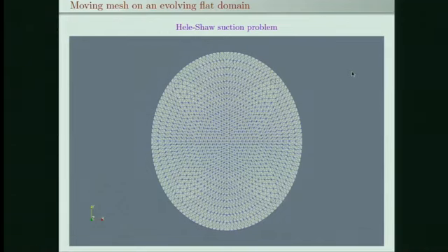We have a discretization on half a sphere, and what we want is a mesh which looks like it's conforming. We're interested in computing approximations to conformal maps. And what you see here is that the mesh quality, as measured by the ratio of the inscribed circle to the circumscribed circle, is pretty much constant in this simulation. The idea is that's a good quality for a mesh.